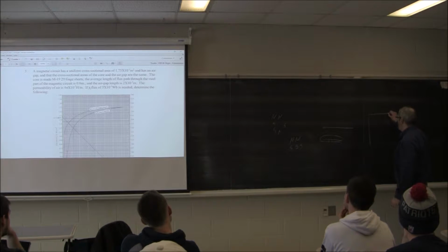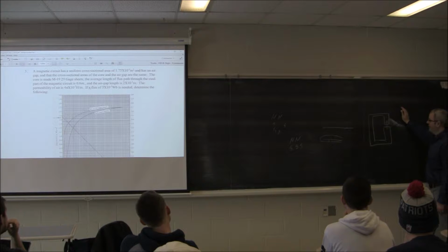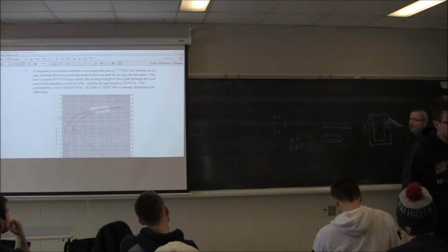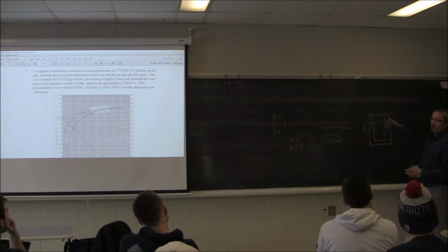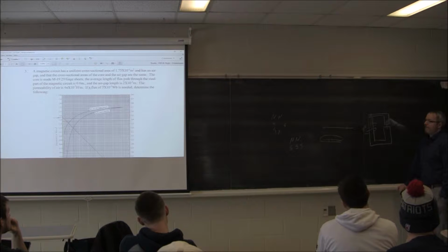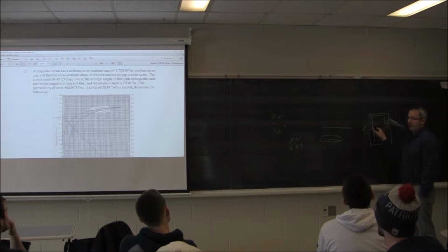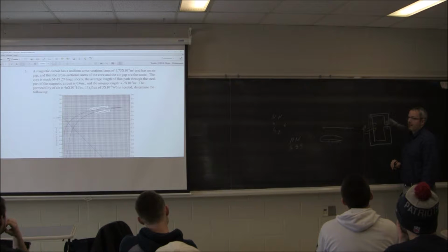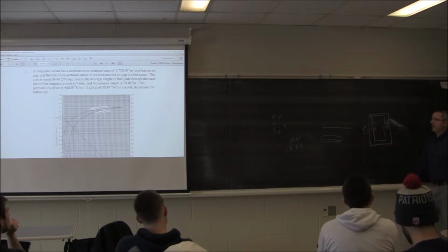You've got flux going through the air. You've got a wire driving a current which forces a flux. So this is I, and that's phi. So the flux actually jumps through the air gap. You don't have any current in here, and you shouldn't. You don't want current going through the air. Where I'm getting lost is how would you solve for reluctance? It's the same process. You have a magnetic circuit. You find the voltage source, reluctance of the metal, reluctance of the air gap, reluctance of the metal. This is a voltage source, a resistor, another resistor, and a third resistor. And the current flow through that circuit is how you're going to calculate what the reluctance is.